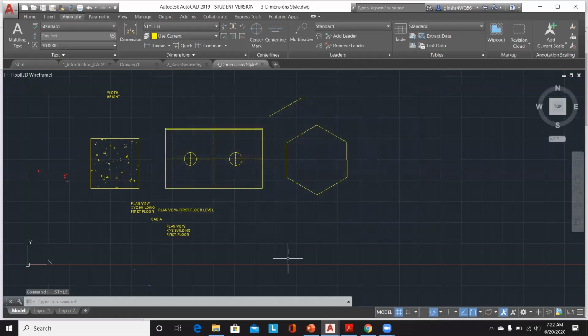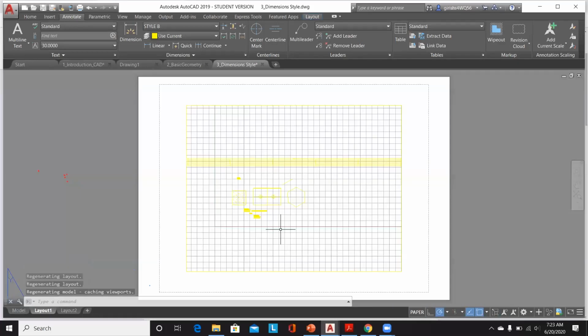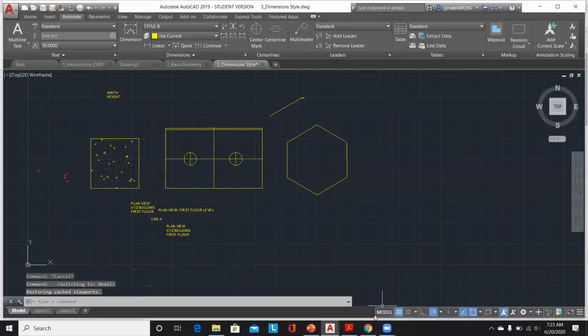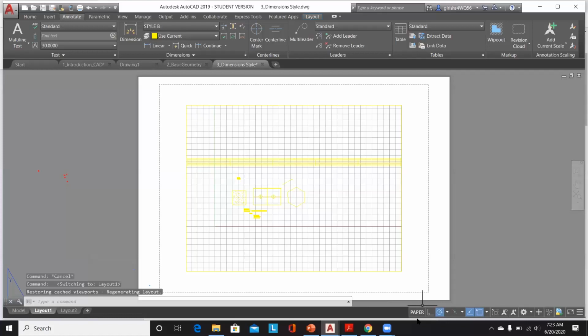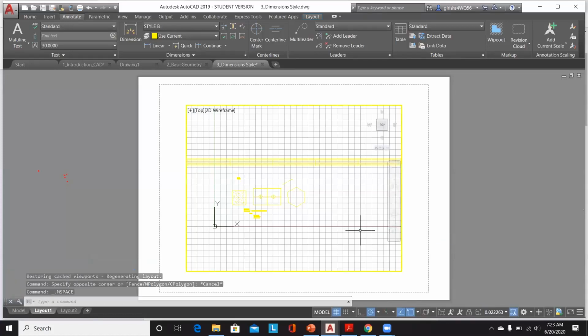Yeah. So there's this question from Surya, how to fix the scale? Okay, this is a good question. This question leads us directly to the layout tab. We will discuss the layout tab quickly in the next subtopic. When we are in the model space, the model space appears here, and when we get to the layout, it is switched to the paper space. And if you double click, you can see the scale, the metric scale, has appeared.